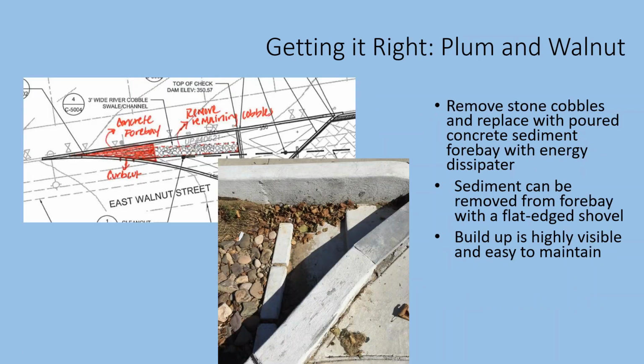So you can see here there's just a simple markup of what we did. We had our field staff go in and remove a few of the cobbles, replace it with a poured concrete forebay with some energy dissipation practices in there, making it a lot easier for our maintenance staff to go in with a flat edge shovel to remove the accumulated sediment. And it's also more readily visible. So when these forebays begin to fill up with sediment, it's easier for my inspectors to say, hey, there's a problem, or for our maintenance guys to say, oh, this is one that we have to get on right away. Next slide.